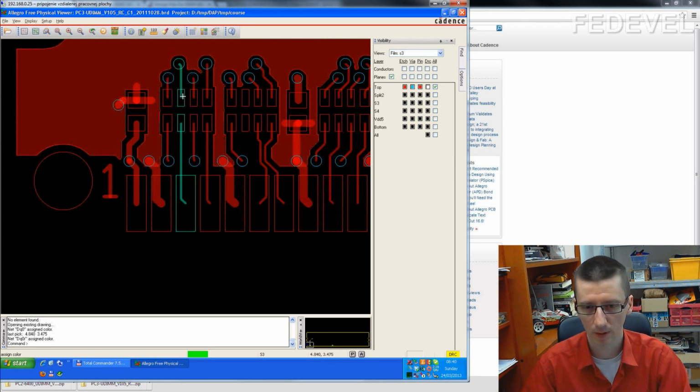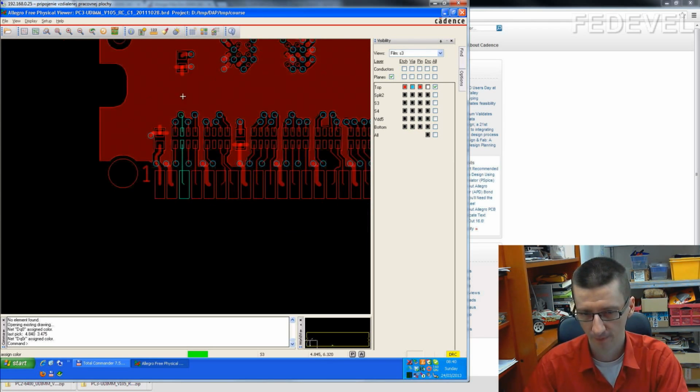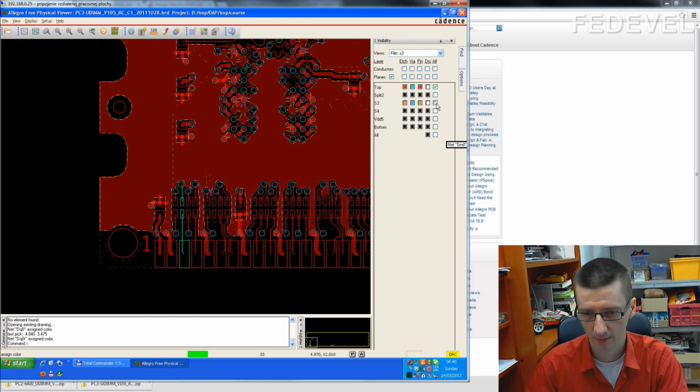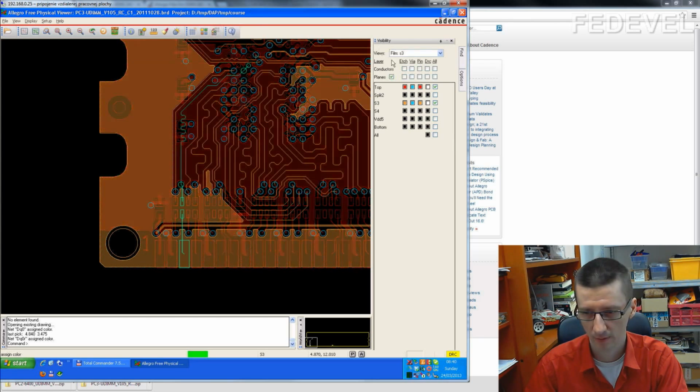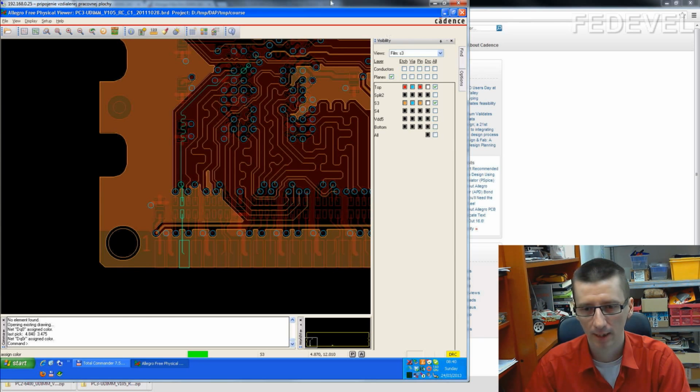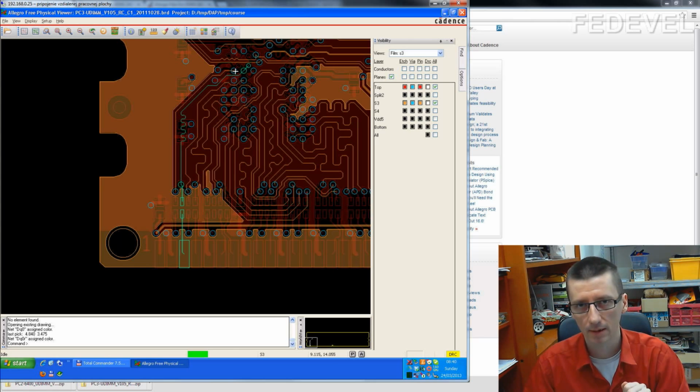Okay, and see where it continues. There is actually no difference between DDR2 and DDR3 memory in the data line connection. As you can see, it goes from the pin to the termination resistor and to the memory. So that's a pin-to-pin connection. What is different is the connection of this address line.